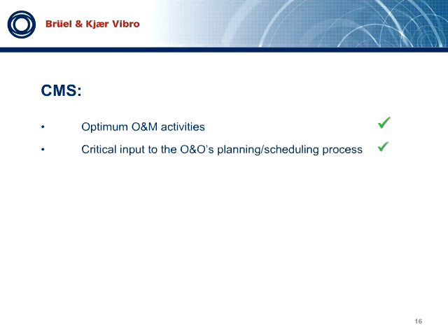So, CMS can be a very strong tool to have when you're trying to optimize the different activities associated with these machines. This could be priority of repairs, better utilization of available resources, and fast up-tower troubleshooting in terms of fault finding. You don't necessarily need to borescope the whole gearbox. You can go straight to the component that the CMS has identified. Planning and scheduling. Planning is just so important here. Even a skilled team does a poor job if planning is poor. And last, it helps ensure the fleet meets and even exceeds the design life if you use it correctly. You've got to use it.